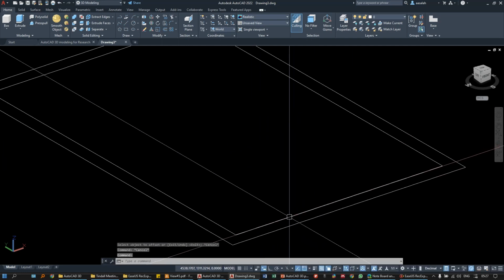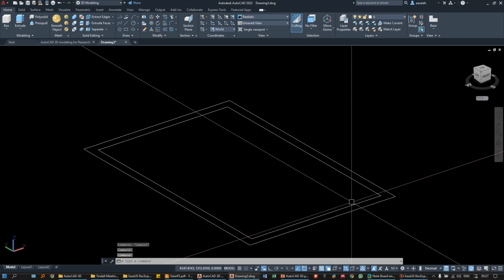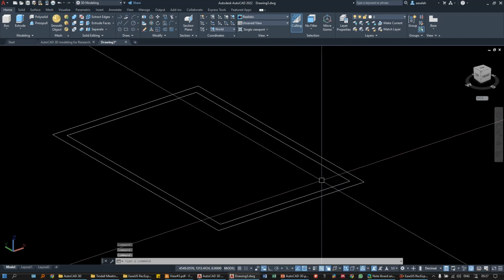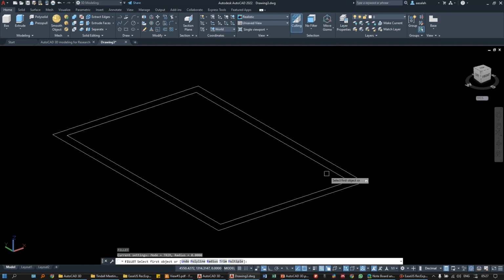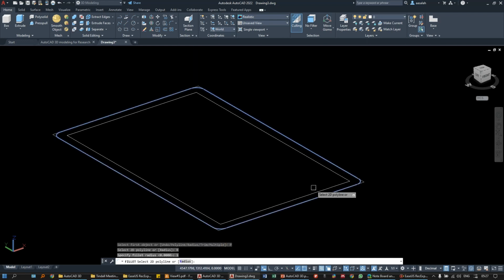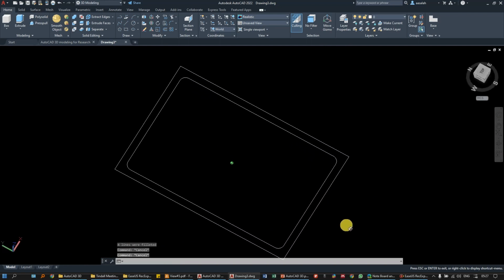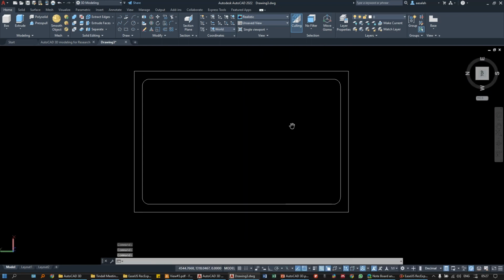So this is going to be my stirrup, and then I have to make a radius for the corners. I need to make them curved. So I'm going to use the fillet command, then select polyline, and then adjust the radius, let's say 1 inch, and then you just select this one. As we can see, now we have the column.